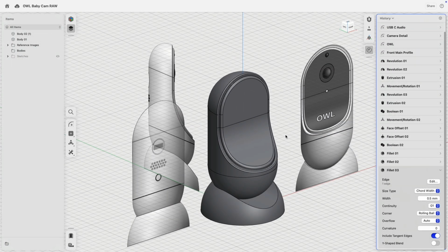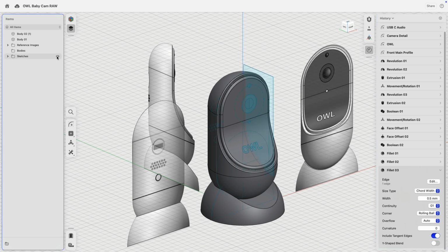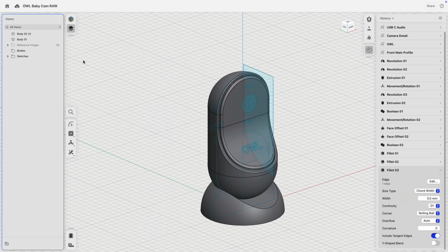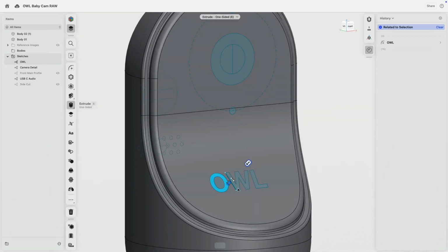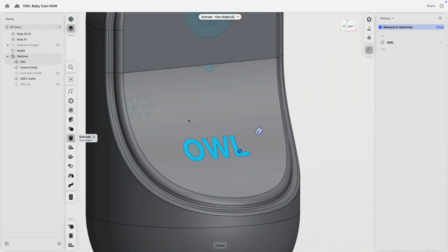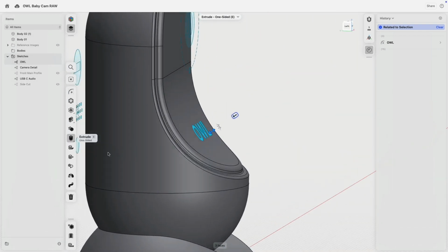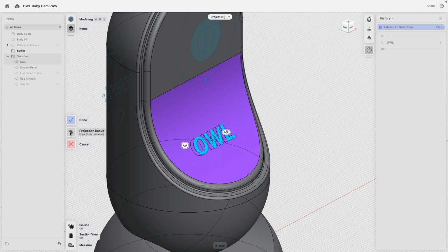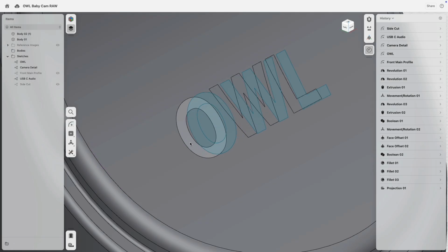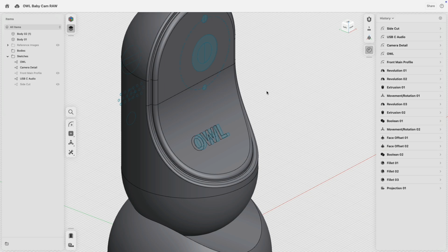Easy peasy. So with the front detail now, how do we do all this? This is maybe a good moment where we can show our original sketches again. The profile side cut we can hide, and maybe from the bottom to the top, I work up. So here, all this I will select, and then I can project this onto that surface. Edge only on faces, so these faces are cut, and I can give that later a different material.